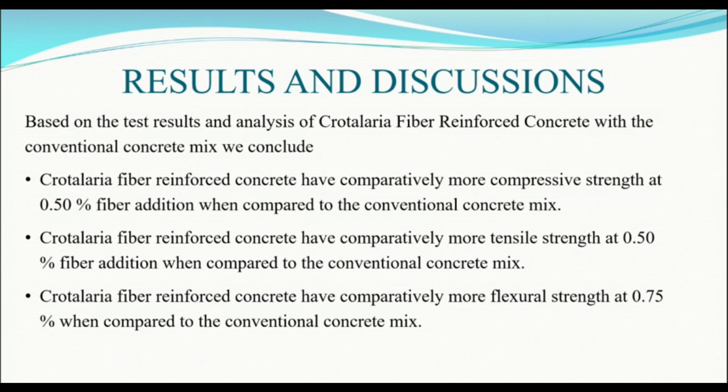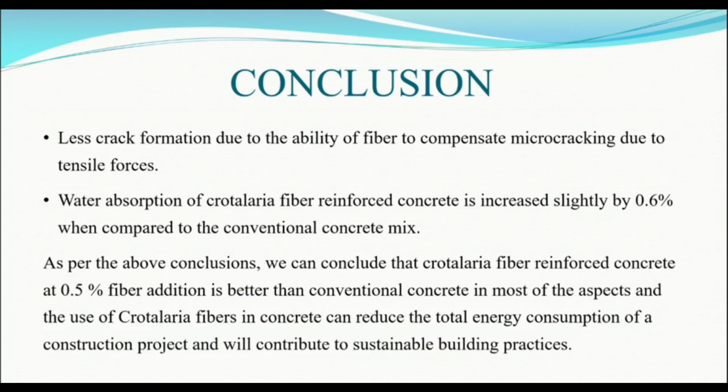Crotalaria fiber reinforced concrete has comparatively more tensile strength at 0.5% fiber addition when compared to the conventional concrete mix, and comparatively more flexural strength at 0.75% when compared to the conventional concrete mix. The results indicate that there is an increase in compressive strength, split tensile and flexural strength with respect to that of plain concrete, varying from 0.25, 0.5, 0.75 and 1%.